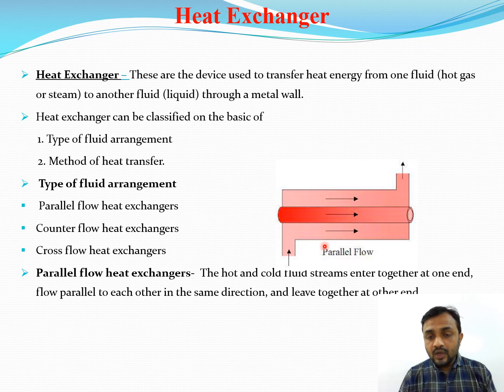Okay, so the hot and cold fluid streams enter together at one end, flow parallel to each other in the same direction, and leave together at the other end. Then this is known as your parallel flow. Here your hot fluid flows in this direction and the cold fluid also flows in the same direction. Okay, if this flow happens, then this is known as your parallel flow heat exchanger.